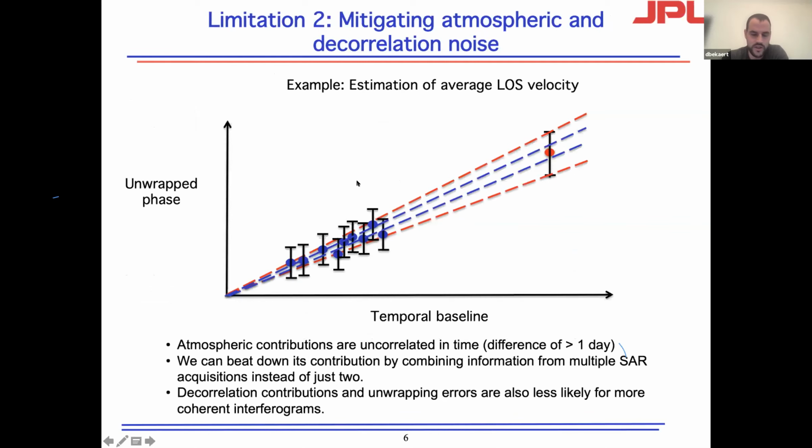So the other component is if you're looking at a single interferogram and you're trying to estimate a rate. That's illustrated here by the top right dot, where the error bar gives you kind of the atmospheric variability. You can always take the temporal baseline which was used for making that interferogram, so you could just ratio the cumulative by that temporal baseline to kind of get a rate. That will have a larger uncertainty if you only have a single image versus if you would be able to recover a whole time series of many individual epochs.